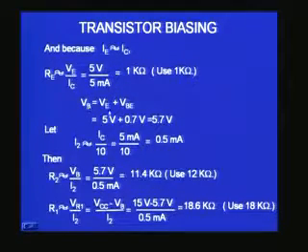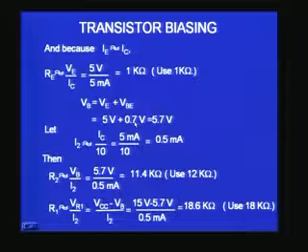And what is Vb? Vb is Ve plus Vbe. We wrote previously Ve is Vb minus Vbe. Now we are writing the other way. Vb is equal to Ve plus Vbe. Ve is 5 volts because we have just calculated or assumed, plus Vbe is 0.7 volts, assuming that to be a silicon transistor, and the total voltage Vb should be 5.7. So we want this to be 5.7. That means I must make sure that the R1 and R2 values are chosen so that the value at the base will be 5.7 volts. Then we have designed the biasing circuit according to our initial starting specification.